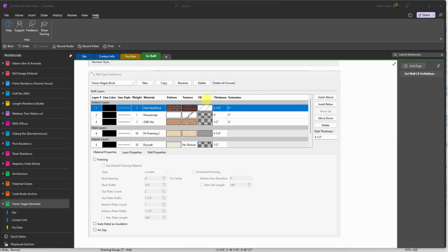So then my brick veneer, I'm going to take that back to be perpendicular to here. And you can see it's got a little bit of that weird offsetness, but that might be useful to keep track of some stuff here. And so I'm going to come out to this point, then I'm going to trim back.